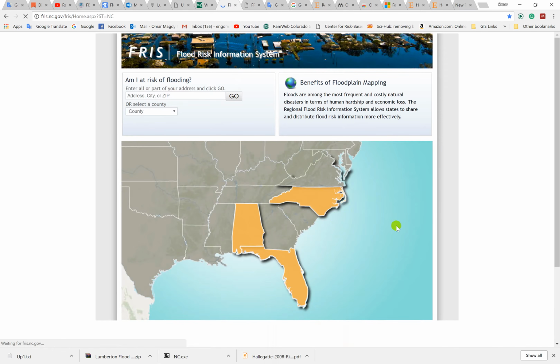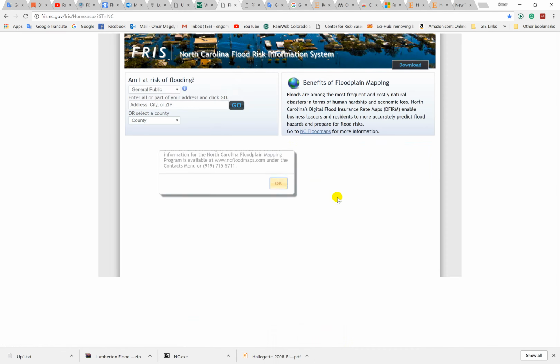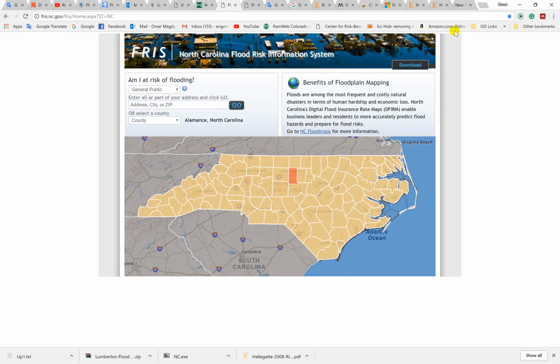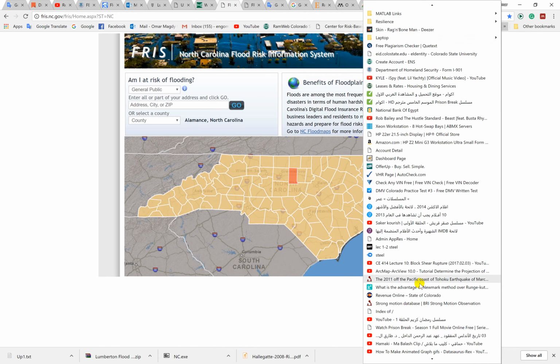And I got a very useful website. You just say the flood height is that, and it will make a flood plain and show you the most damaged buildings in red and the others in blue. And it also calculates the cost. The state of North Carolina developed this website. But I don't think it's accurate, because the flood plain doesn't look the same as what happened in reality. They maybe use a specific algorithm or something like that, which is not really accurate.